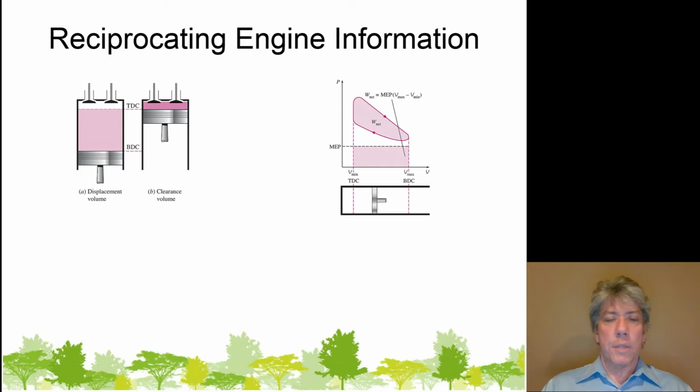In fact, I just bought a car and it has a 2.0 liter engine. What that means is that 2 liters of volume, of air essentially, well, really volume, is displaced every thermodynamic cycle, which is 2 rotations of the crankshaft. If I got my facts right, maybe every single rotation. I don't think the engine's that big. No, it must be every 2 rotations for a complete thermodynamic cycle.